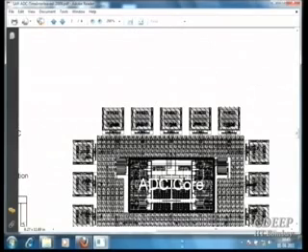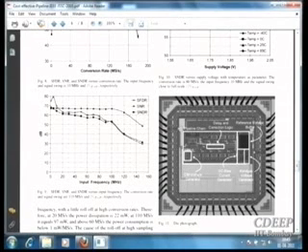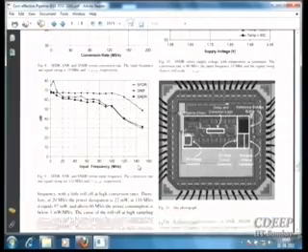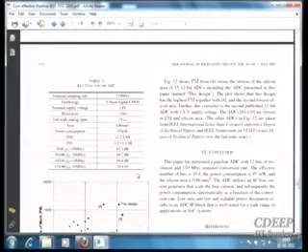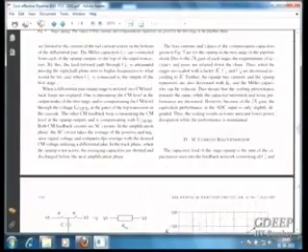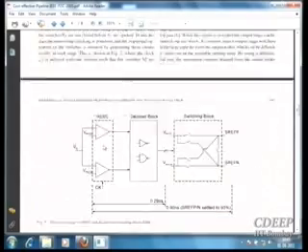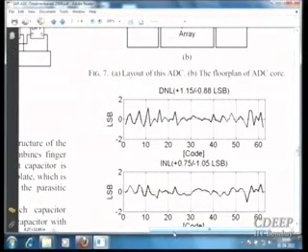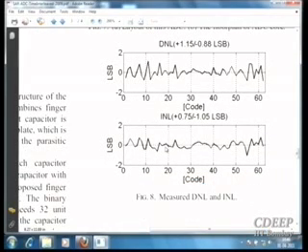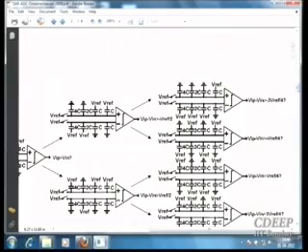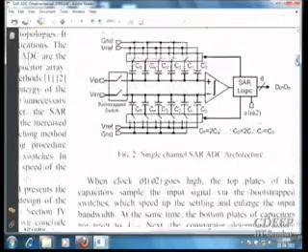Okay, so I think with these 2 examples, you don't need to make a layout, by the way. You will do only the schematic level, and then you will make a table similar to this. For example, DNL and INL, I will get back to your question. DNL and INL are given here. See really how much offset can lead you to these values. And here I think they don't have it. They have not reported offset compensation.